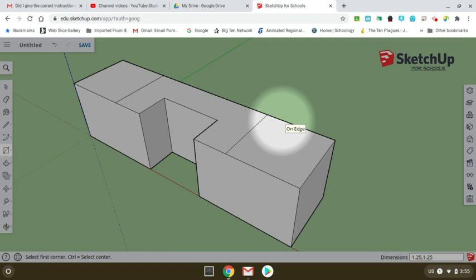So we will now need to, because we have to remove part of this because we have to create like a tongue here, so to speak. So now we're going to recreate or create another rectangle. So I'm going to start at this point, and I'm just going to drag over to this point and click there, and it should be locked into the dimensions we need. And I'm going to do the same, start at this end point and come to this end point. And again, it's what we need.